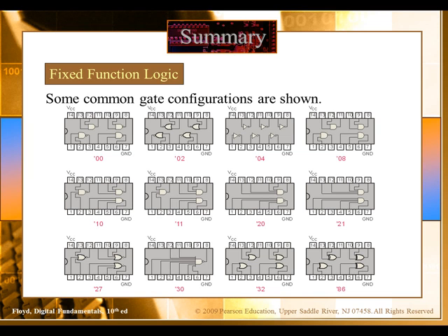We'll also know which IC to use. This is one example here. Let's say you need inverters. Which one do you use? 7404, right? All the inverters are here. Do you see the inverters? Now let's say you need only 1 inverter in your circuit. Still you have to use the whole IC, right? In the whole IC you have 6 inverters. You see, there are 1, 2, 3, 4, 5, 6 inverters here.